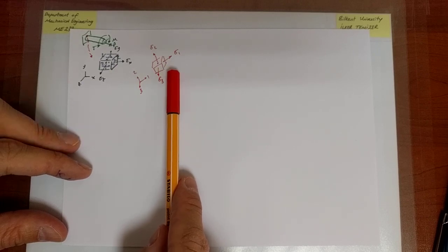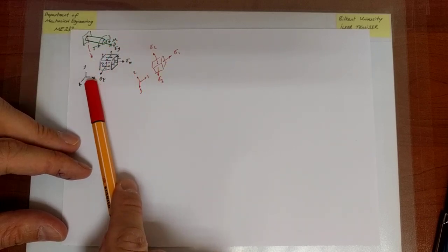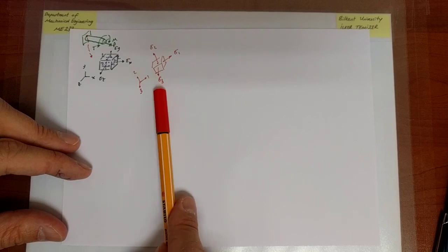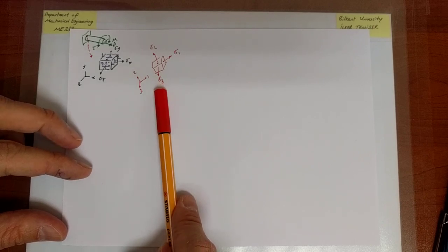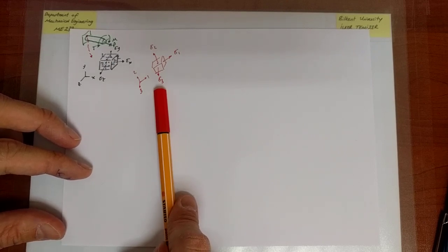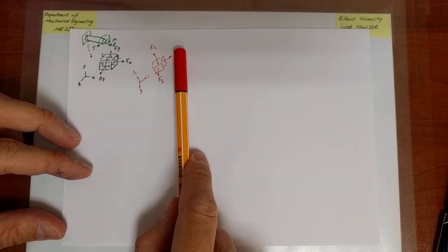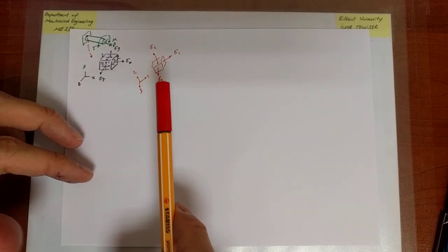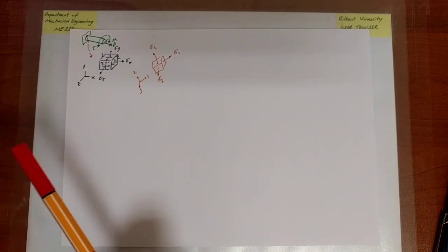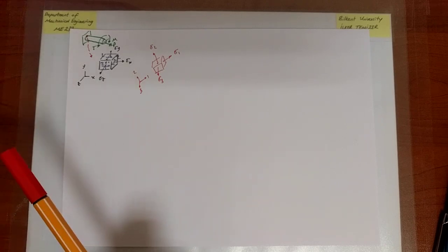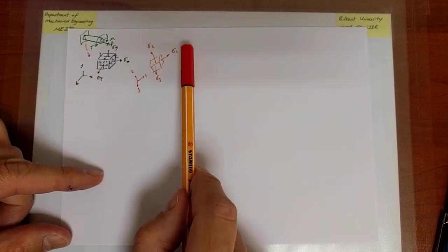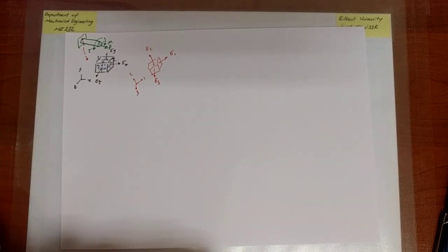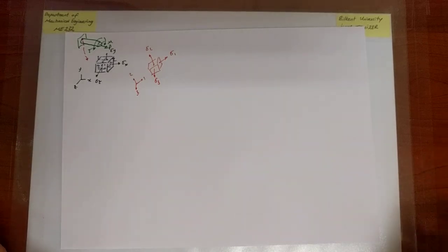And this has a conceptual advantage because here there are 6 independent components of the stress, whereas here there are only 3 independent components that influence now whether or not failure is going to occur. If there is only one stress in general, so it's essentially uniaxial loading, I know when, for instance, a ductile material will yield. It's going to yield at sigma naught. But if there are 3 principal stresses, then the question is, when does yielding occur and if it occurs at all? And the same question is going to be asked for a brittle material as well.